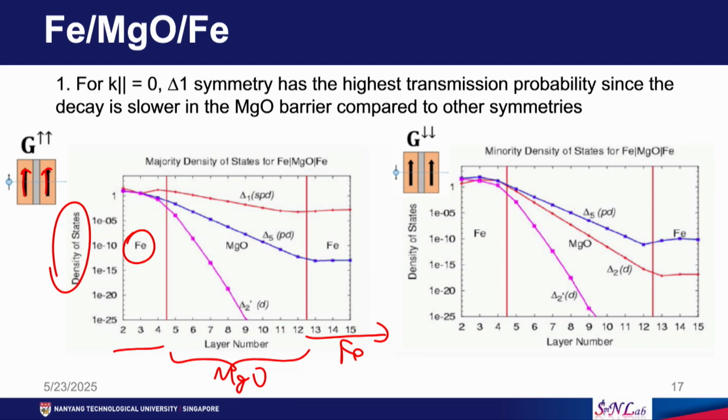Okay, so, if the difference in the density of states is not much, then we can say that the band matches and the probability for an electron to tunnel from this side to the other side is higher. Okay. If, for example, this band does not match, here there is a large mismatch and so on. So, this means the tunneling probability is less and here may be almost impossible.